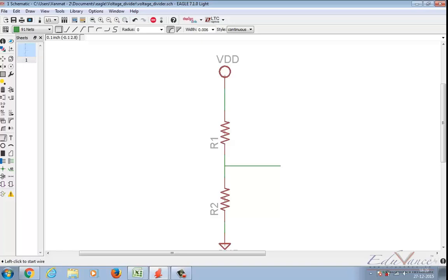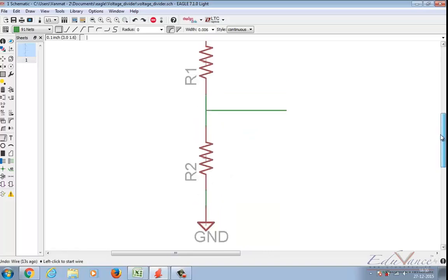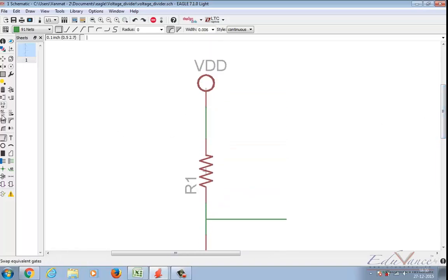Okay, now I need to physically provide voltage supply and ground connections to the schematic, so I will make provision for the same. Let's take one more wire from here and leave it here as of now. This is going to be our VDD. We will still need to provide VDD and ground, so select your wire tool, click on the middle and just select a wire here.